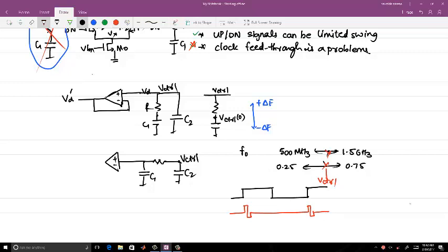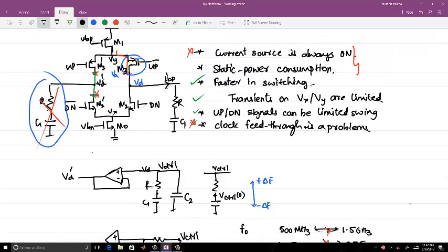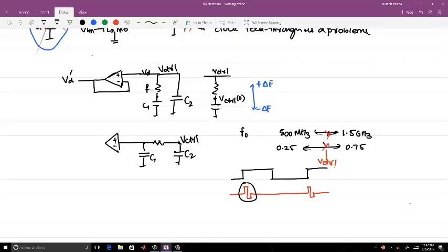So when you inject these currents onto the charge pump, your V control voltage will change accordingly. You are not changing the PMOS current source drain voltage for that, because if you see, the average of that is still zero in a steady state.